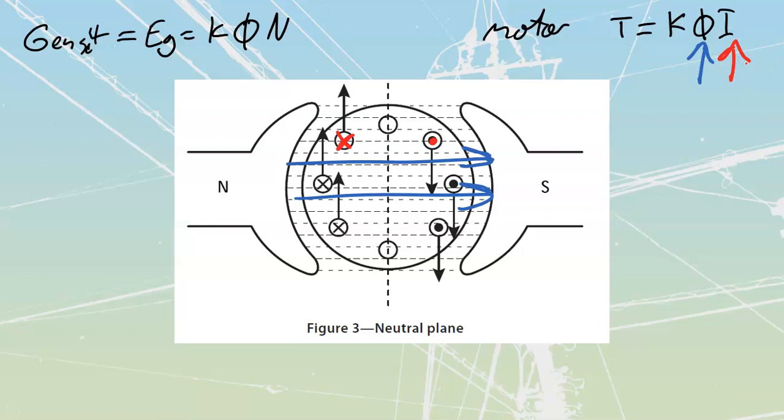So with an increase in either one of those, either I'm going to have an increase in armature current, which is going to cause bigger circulating magnetic fields, which is going to distort it more, provide more thrust. Or if I provide more main field, the blue lines over here, that's also going to provide more thrust, more torque off of it. The K stays the same for these ones over here.